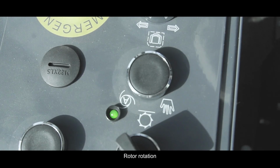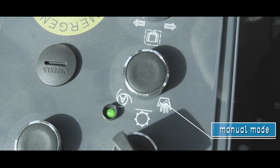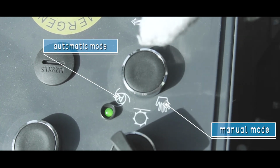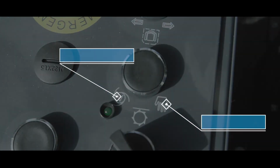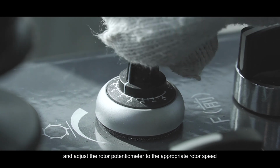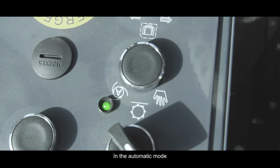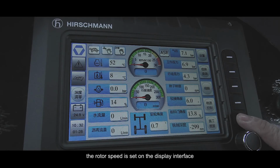Rotor rotation. First select the rotor drive mode, manual mode, or automatic mode. In manual mode, turn on the rotor drive switch and adjust the rotor potentiometer to the appropriate rotor speed. In the automatic mode, the rotor speed is set on the display interface.